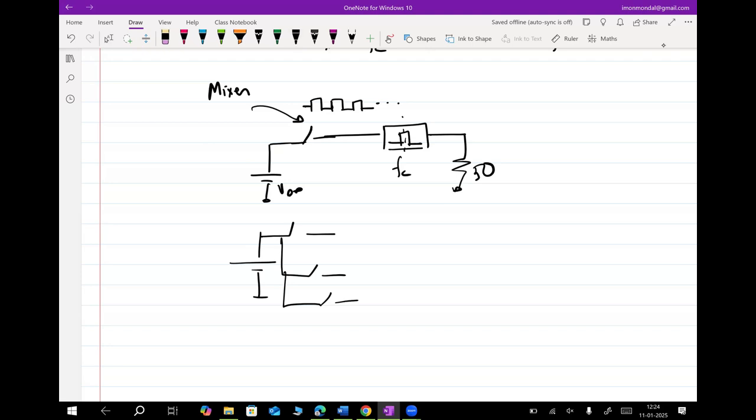In this case, I can break it up into 2 paths and make it a differential antenna. I can put a balun or inductor, right? An inductor having some sort of mutual inductance. Assume a transformer, an ideal transformer.